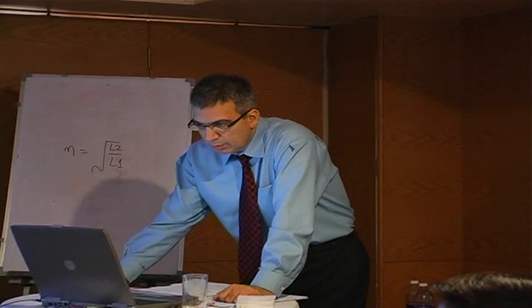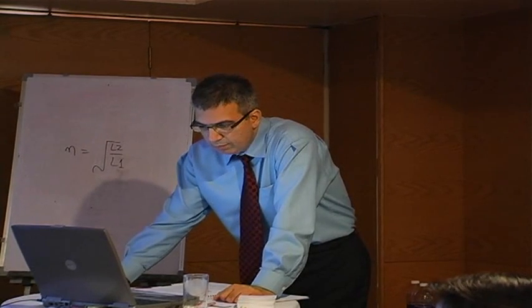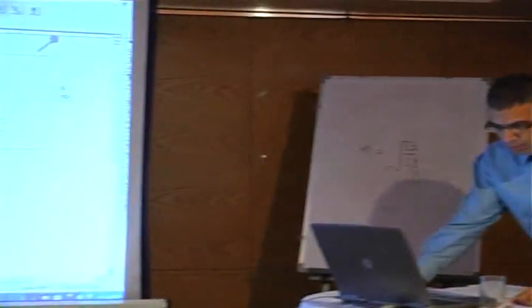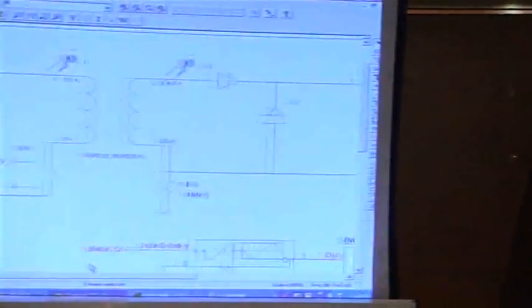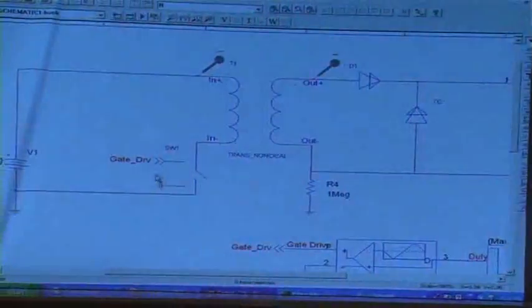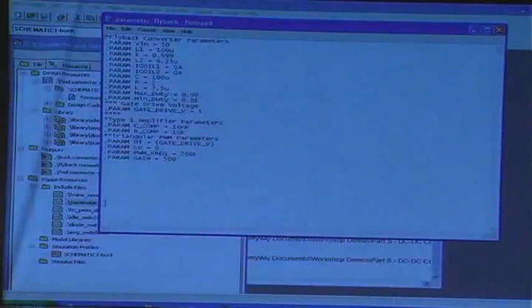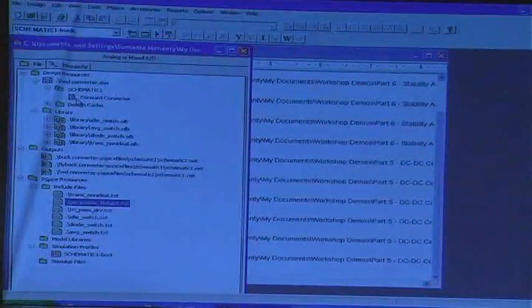So the polarity of the transformer is such that when you have current flowing here, you have current flowing in the diode. We have V input of 50 volts, L1 of 100, L2 of 6.25 microhenry, C of 100 and R of 1 ohm, sitting at 200 kilohertz.